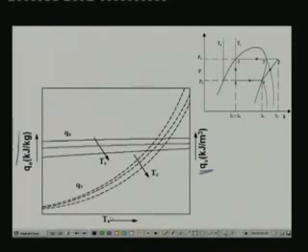And you can see here that on the x axis I have evaporator temperature, and I have got these performance parameters for different values of condenser temperature. So, you can see that condenser temperature is increasing in this direction for specific refrigeration effect, and it is increasing again in the same direction for volumetric refrigeration effect. From this graph you can easily see that as you increase the evaporator temperature for a given condenser temperature, there is a marginal increase in specific refrigeration effect. Okay, and the specific refrigeration effect also increases as condensing temperature decreases.